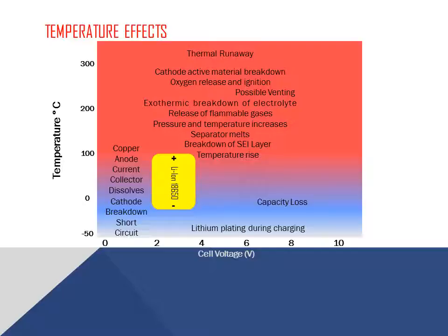Likewise, lithium-ion batteries are not very efficient at drastically low temperatures, especially during charging. As shown in this figure, lithium-ion cells start losing some of their capacity right at freezing point. As temperatures drop even lower, the diffusion of lithium ions is so slow that lithium plating may happen. Please note that this is also dependent on the battery's history, state of charge, and chemistry.